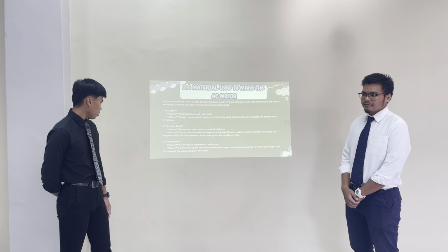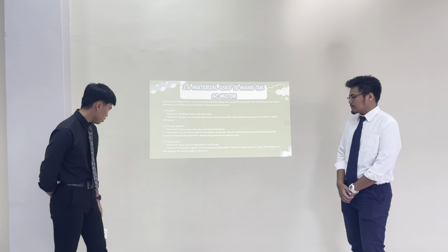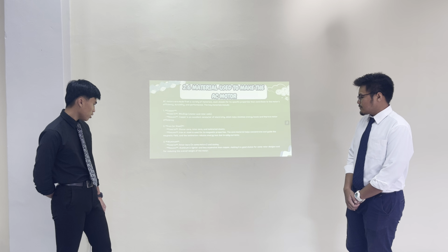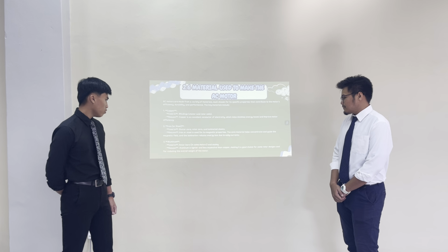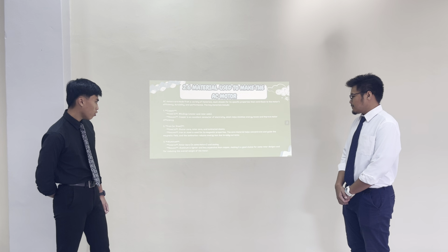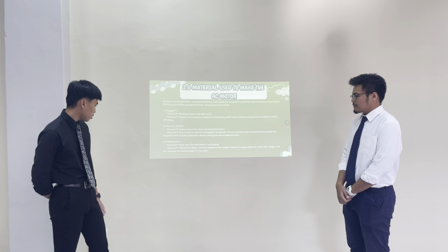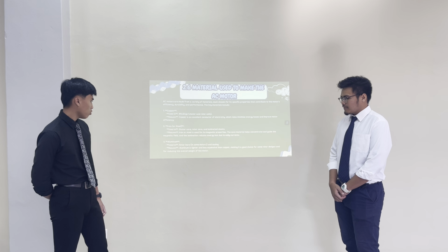Aluminium, used in rotor bars in some motors and casing. Reason: aluminium is lightweight and less expensive. The conductivity makes it a good choice for some rotor designs and for reducing the overall weight of the motor. Next,